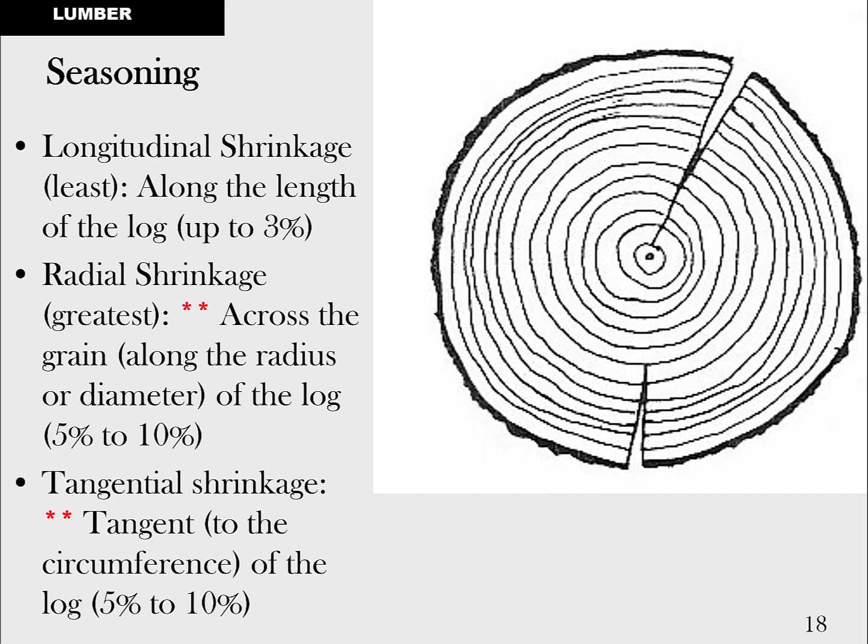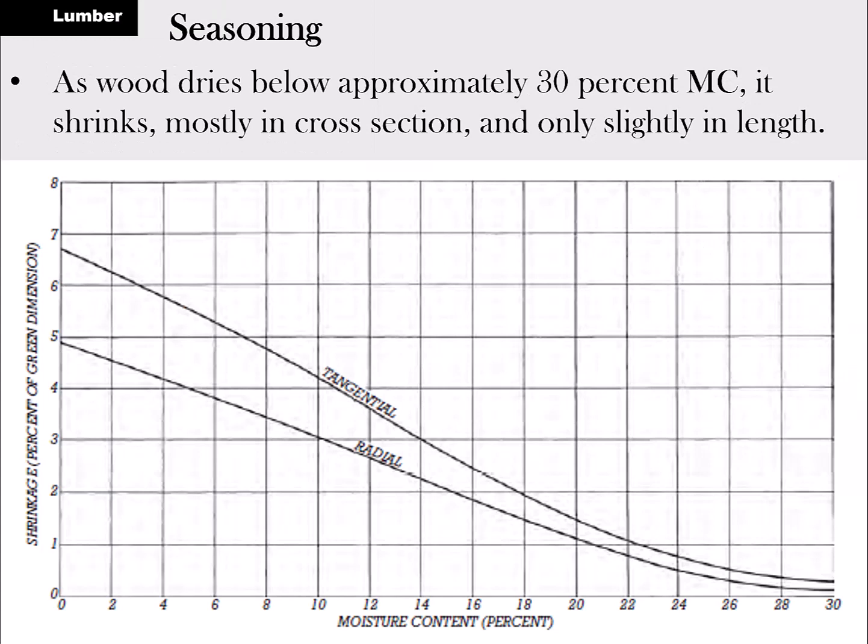And the wood cells run lengthways. They're not perfect round cells, and they tend to run along the length of the log too, so the cell shapes themselves give you something to go by on that. Okay, so yeah, the tangential and radial, there's a factor, but really this graph kind of shows that tangential shrinkage is a bigger deal than radial. But the author of the book that I based this course on, he was going for radial. I say at best they're equal, and so I'm going to consider them both equal, and we're not going to worry about that.